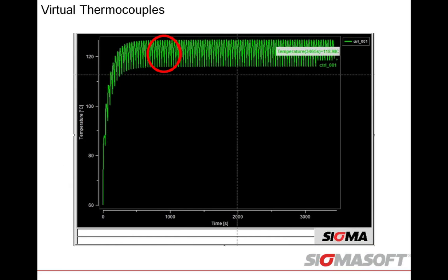In this case, I'm looking at a thermocouple where you can see we definitely have a temperature increase here, and then just shy of maybe around 1,000 seconds after multiple cycles, we start to see that leveling off, and then it's pretty consistent for the rest of the run. And how valuable is this, right? To really understand when that mold reaches steady state before you ever put it into the machine.